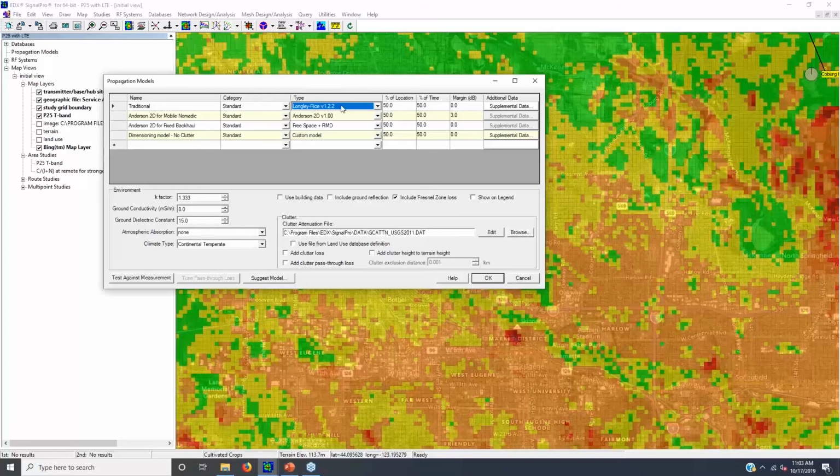In the old days, I would just do a received signal map, and I wanted to apply additional loss to my prediction so that if I predict a given signal level for one grid location, then say 90% of the time out in the field, I'm going to measure a higher received power value than what I predicted. And so I would increase these to 90%. The amount of additional loss was based on tables provided by the NTIA for how much fading we expect to see over time and how much Rayleigh fading.